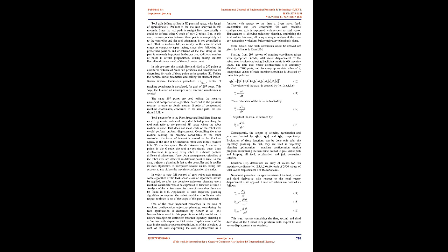The desired pose coordinates are input in this algorithm, as well as the ideal machine coordinates, used as initial guess. The algorithm iteratively makes deviation reduction in order to get as close as possible to the desired pose, in the pose space, to some predefined tolerance. That also comes as input in the algorithm. One additional input value is needed, the iterative step, as a measure of machine coordinates changes in each iteration. In the first iteration, machine coordinates are set to the initial guess values.